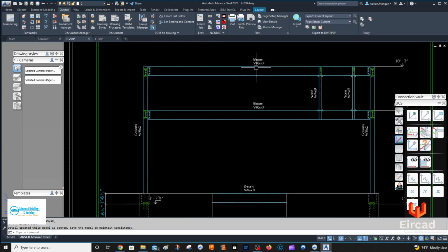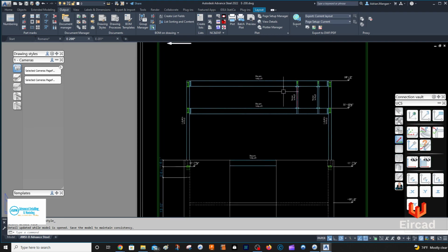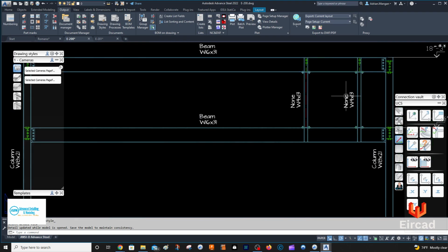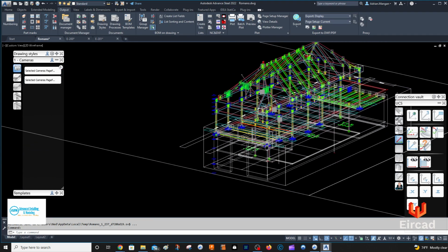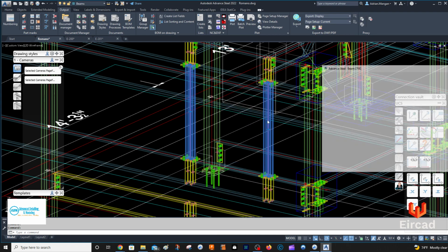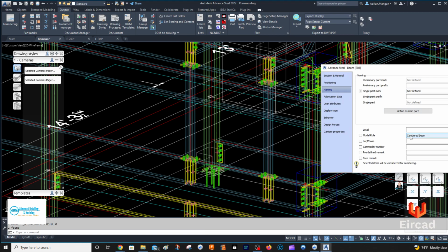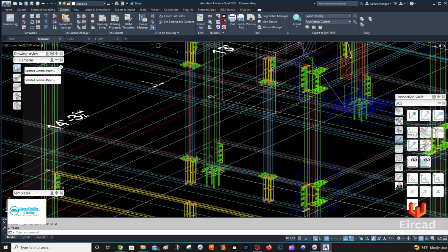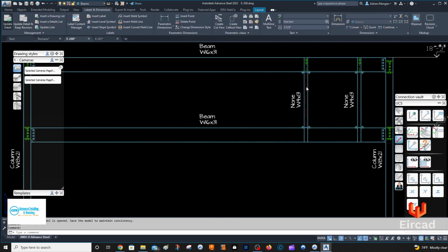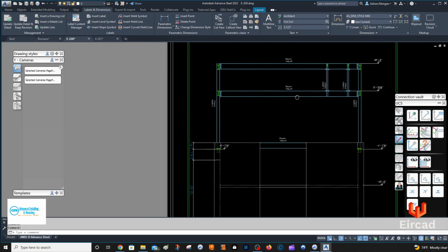They have not been numbered, so it's not giving an end of the beam. And these ones don't have, as you can see, a model role. So straight away we can go back and fix that. So let's go back in and fix these two. Advanced properties, naming, column 1, 2, 3, 4, depending on how many model roles you have. So, you know, you can kind of do this as you go, right? So you're just jumping over and back, you're checking things. So column, all right, so those columns are in, and they are in the correct way. That's the way I want them.